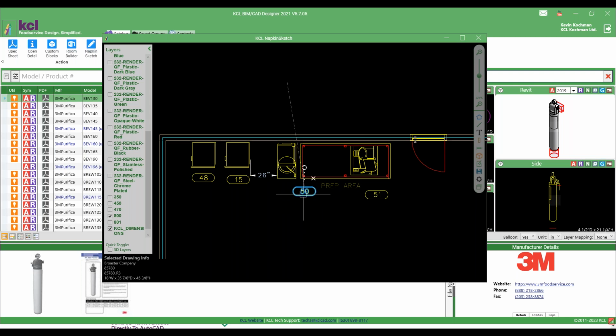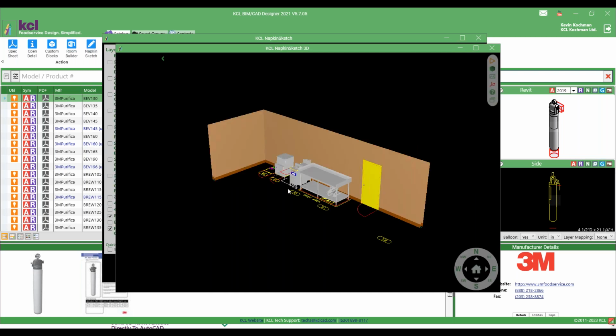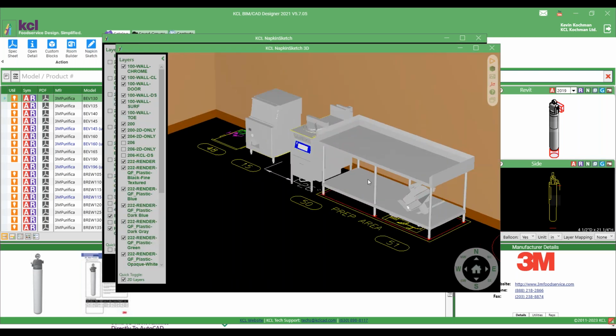Any questions or messages. So now that I have these items in here, I'm going to say, let's go look at this in 3D. We've got a few more pieces. First thing I notice is the globe item was sitting under or on the ground, and I'm going to move it up to the table by changing my height to 36 inches. A simple right click will do that.